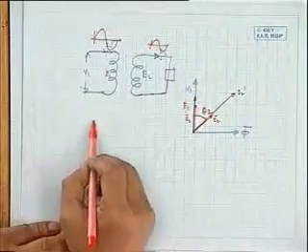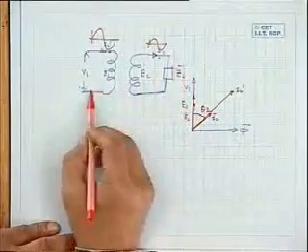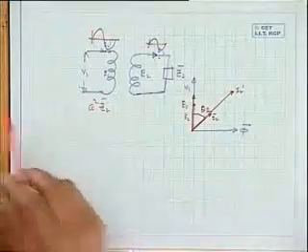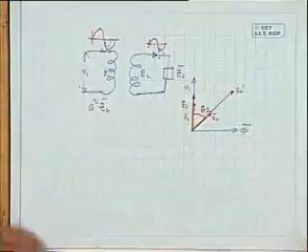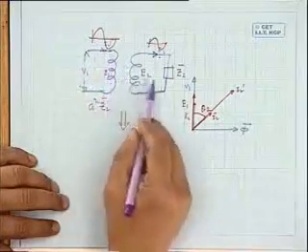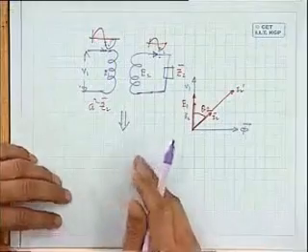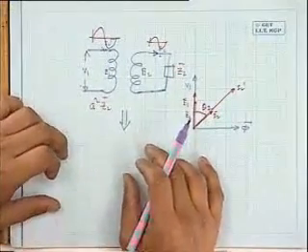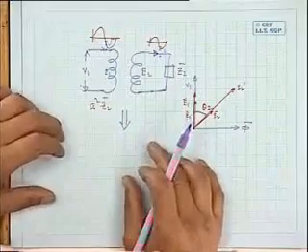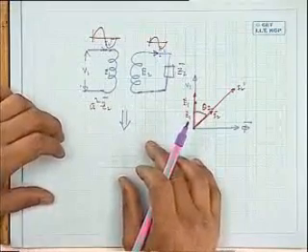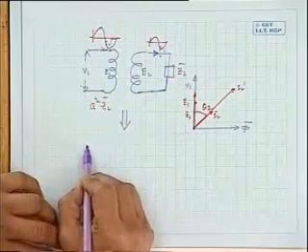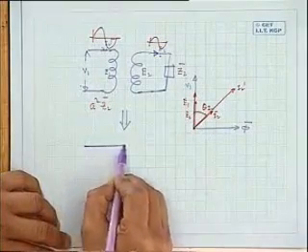So we were discussing the equivalent circuit, and we got that any impedance on the secondary side gets reflected to the primary as a squared Z2. Now, before I proceed further, let us see another interesting thing. Suppose this whole circuit involving a transformer, I want to represent it by a diagram which will correctly represent the no load situation as well as the loaded condition. What I mean to say will be clear if I draw this diagram.